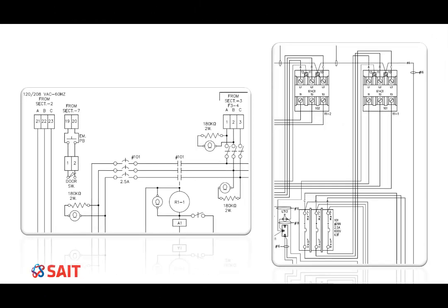Schematic and wiring diagrams are drawn using standards. Standards make sure drawings are created consistently across organizations so that everyone is interpreting the same information. If you are drawing diagrams by hand, you must use a pencil, straight edge, and template. We prefer you use a computer drafting program like AutoCAD. All lines need to be drawn horizontal and vertical in both the schematic and wiring diagrams.